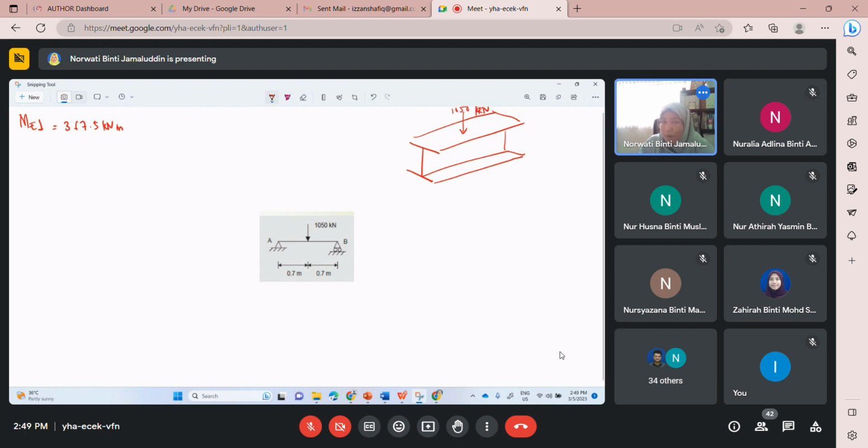Based on this beam arrangement, based on the orientation, the position is as you place it. So this force is a transverse force that results in bending moment around its major axis. This is what the force will do to this structure, to this beam. Okay, bending, rotating about the major axis.